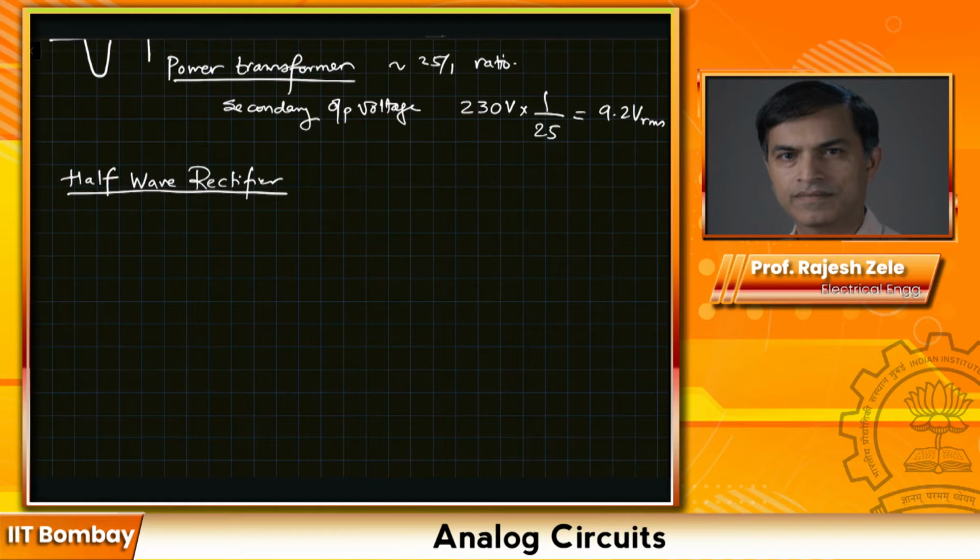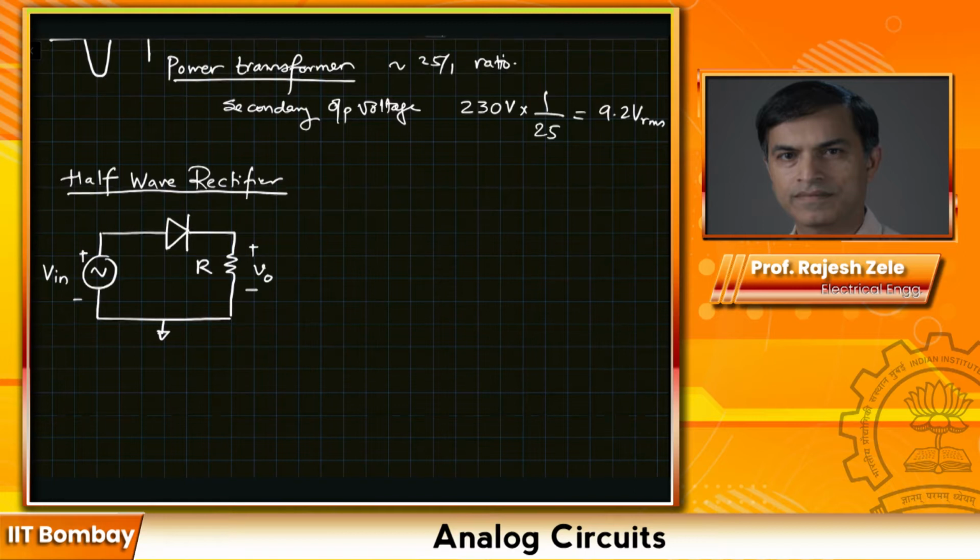And this circuit can be very simple. You have one diode, a PN junction diode. It's connected to a resistor, and here we apply our sinusoidal AC waveform, Vin, say plus minus like this. We can plot the transfer function as follows. We will assume the simple constant voltage model that we learned. We will say that the diode turns on at V_D,on voltage.